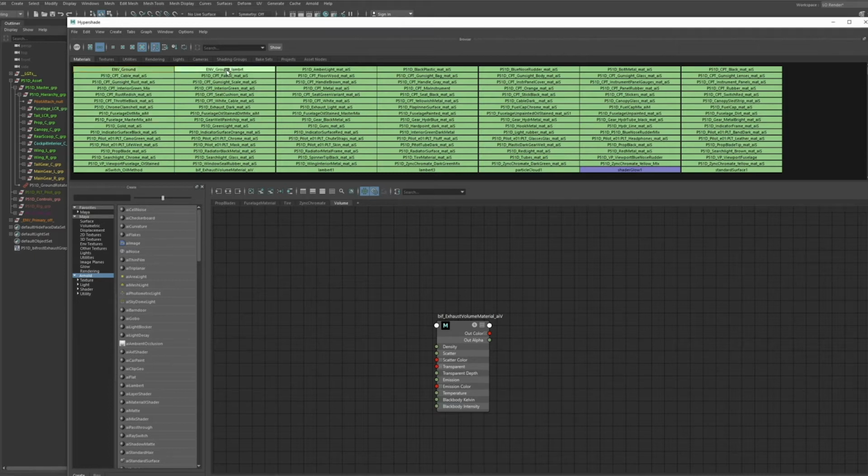So they are prefixed with nth ground, so I know that they do belong to the environment. There's a few things here, a few shaders. This lumbered one is just the standard shader Maya assigns to everything, so that thing exists in the scene. You can access that, but you really never use that. Never change that, actually. If you want to change a shader on an object, assign a shader, change that. Don't change the lumbered one. Things will break if you do at some point.